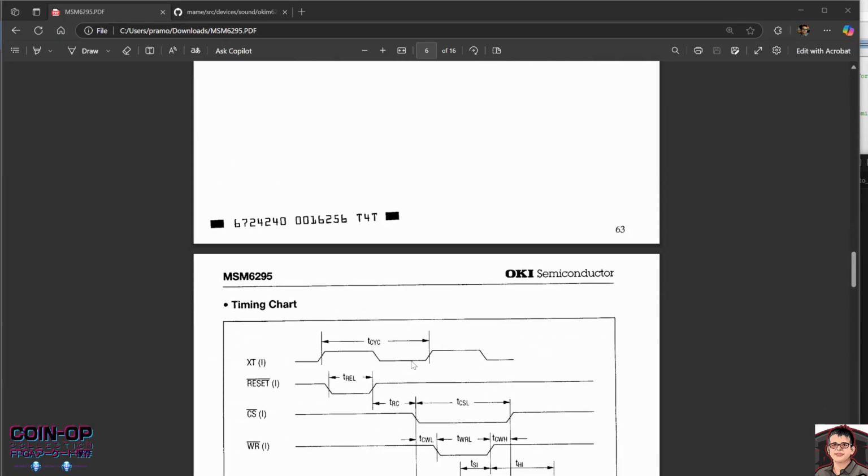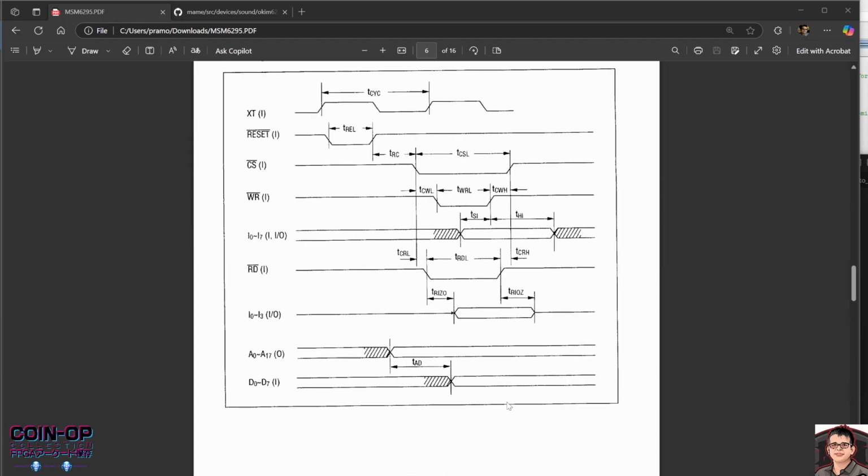The next thing I want to take a look at is the timing charts. In this case, I do take a rough look at the timing chart just to see the cycles that elapse, what the sequence of events are. Mostly, I'm using this for the sequence of events. So I'll use this to determine, let's say a read is to happen, what's the process? Someone asserts a read pin, and then 2 cycles later they get their data and it appears on these pins. Those types of details are something that I would look at the timing chart for.